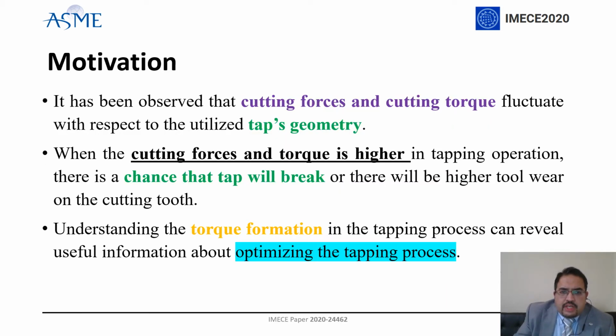If I talk about the motivation involved in the work, so definitely tap geometry controls the cutting forces and the cutting torque. Cutting forces and cutting torque, in some cases when it's higher, can break the tool, can break the tap, and can provide a very high tool wear at the cutting tool. Understanding the torque formation will help us in optimizing the tapping process and provides better understanding.